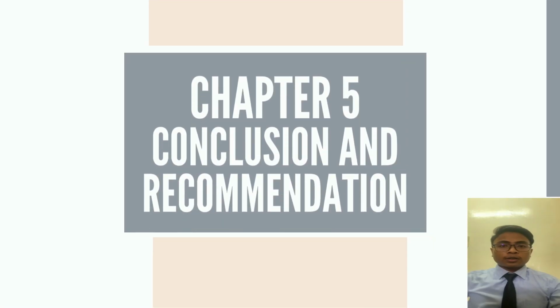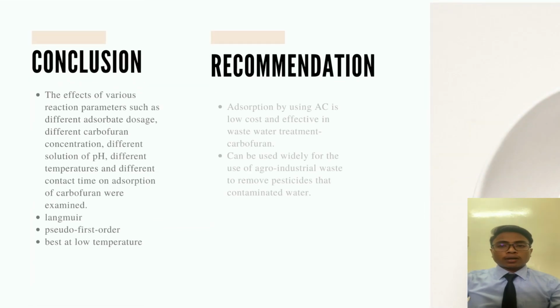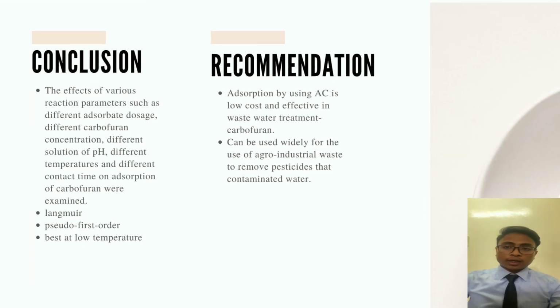Last part is conclusion and recommendation. The adsorptive removal of carbofuran in aqueous solution by granular activated carbon was investigated in this study. The effects of various reaction parameters such as different adsorbate dosage, different carbofuran concentration, different pH, temperature, different contact time and adsorption of carbofuran were examined. Equilibrium was analyzed by Langmuir, Freundlich, and Temkin adsorptive models. The results showed that the Langmuir is the best one, as the Langmuir had a better correlation with the experimental data.